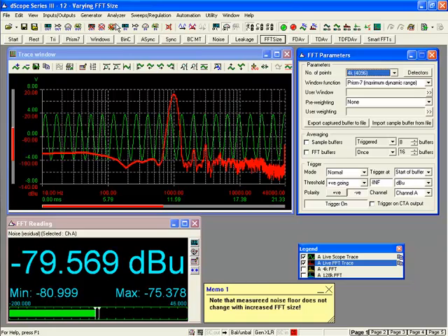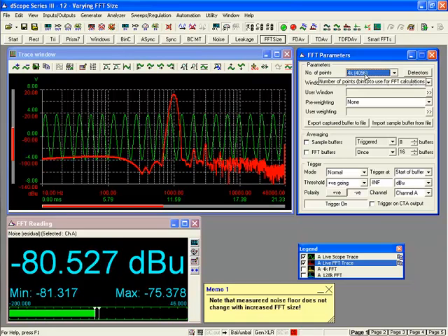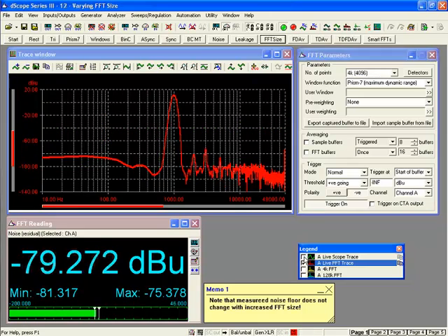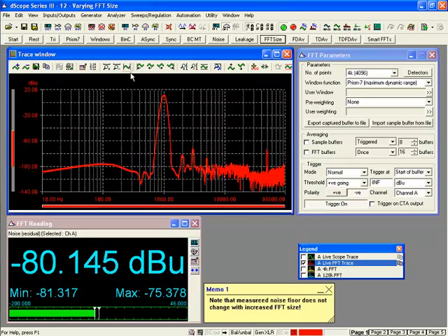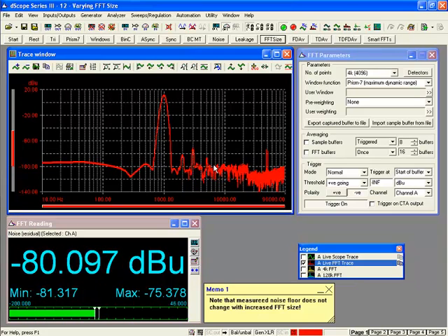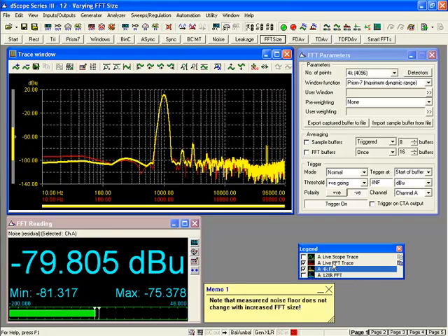So once again, I have an FFT measurement here. I'm using a 4096 point FFT, and that gives me this live result that we're seeing in red. I'll just turn the live time domain trace off, so we can see this more clearly. So this is our FFT trace in red at 4000 points, or 4000 lines you may sometimes hear reference to. I have a copy of that here in yellow.